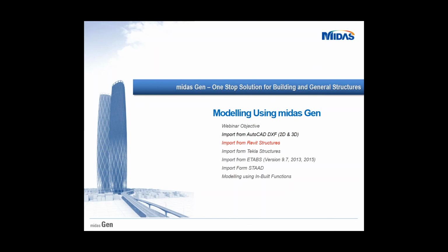And another question from Mr. Amar Dosari. What about the openings in slabs? Sir, if you're modeling the slab as, for example, if in AutoCAD you're modeling the slab as a 3D face and you're providing an opening in that, the opening is also taken care of by the program. Automatically, it will import the opening as well, if it is modeled as a 3D face.